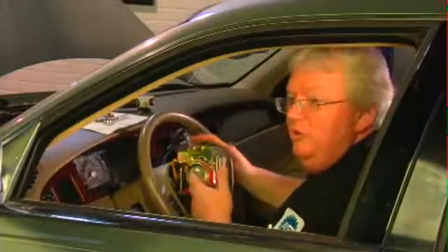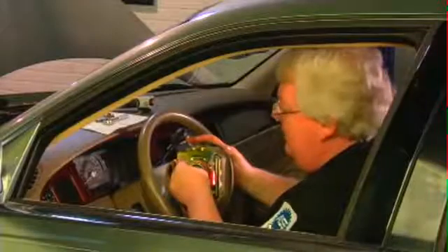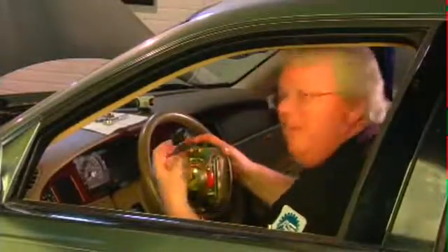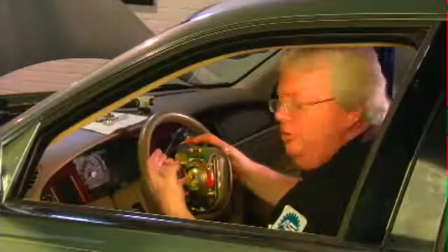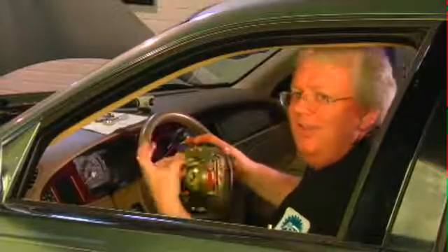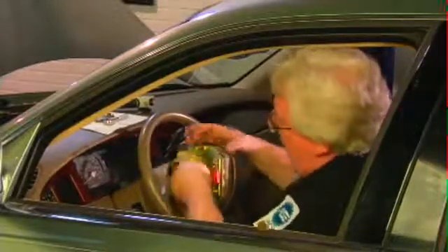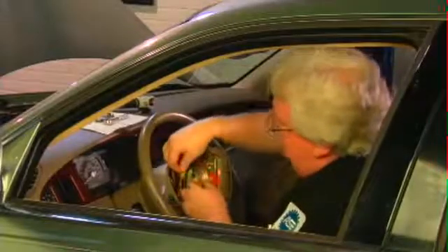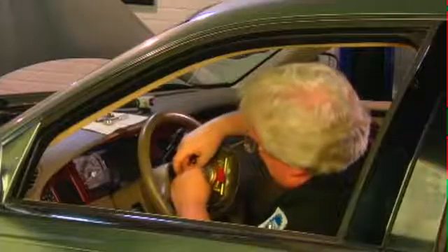This is a two-stage. Both stages are deployed for a bigger airbag under a larger collision, a more rapid deceleration, a more severe collision, and just one stage if it's a lesser severe collision. So I'm going to go ahead and depress these and pull them out, and we see this is black, this insert, and what color is it right here? It's black as well. So make sure you get that right when you go do airbag removal after you've done the depowering of an airbag.